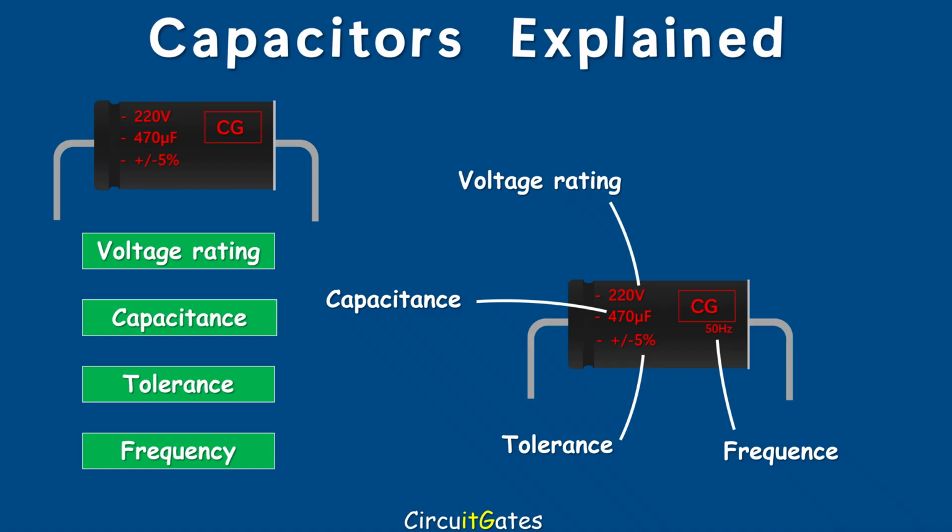A capacitor should be connected to a voltage supply that corresponds to its voltage rating, as higher voltages than its rating damage the capacitor. Tolerance is the amount by which the capacitance of a capacitor varies from its stated value. It is important to use a capacitor with a tolerance value that suits a circuit, so that the circuit delivers the desired results. The capacitance of a capacitor is crucial in determining the amount of charge it stores, ensuring it provides enough power for a circuit's needs.